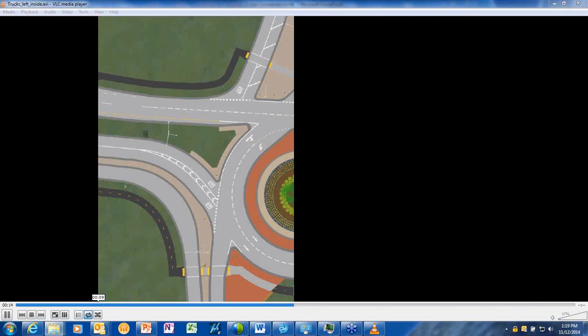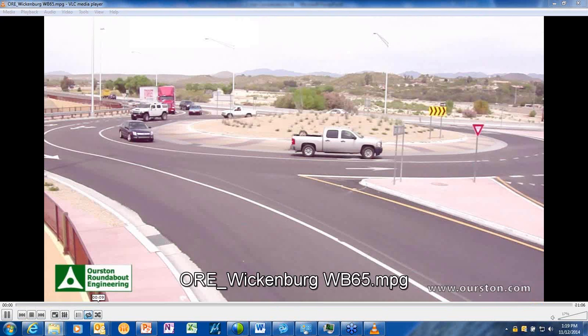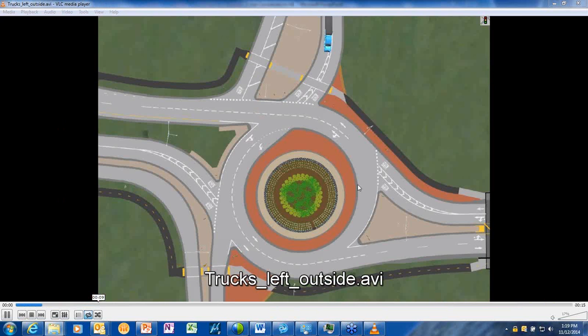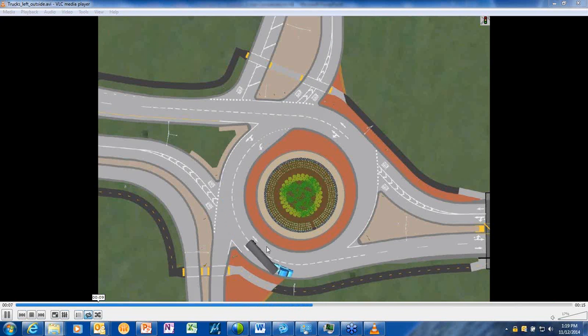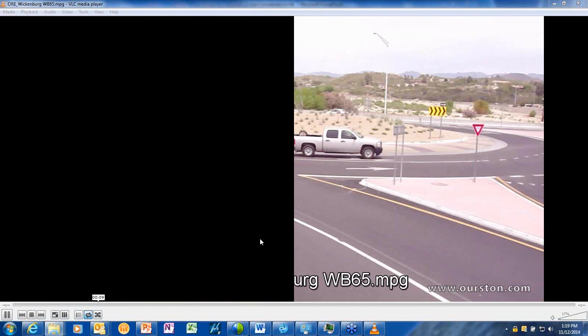The thing about the Case 2 design is that what we try to do in this graphic, it shows it well, that there's still about 9 feet of space. Even if the rear wheels of the truck do overtrack, there's space for a car not to be squeezed into that. So if they do try to pass the truck, they're not going to get crushed.